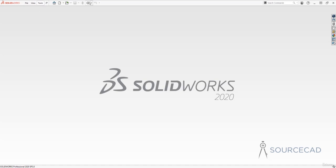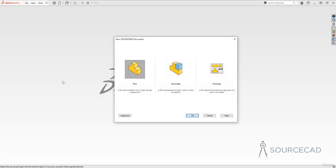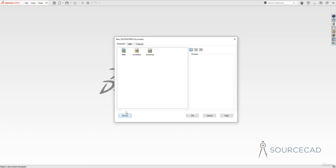Then we have the quick access toolbar, which we'll explore in a moment. So let's now start a simple blank template. I'll go to File and New. And here you can select a template like Part, Assembly or Drawing. This is the novice view. You can also switch to Advanced view to see more templates. These three are the same templates which we saw in the novice view, but we have some in the MBD tab, and you can add your own custom templates in the tutorial or anywhere you want here. So I'll switch to templates, select part, and click OK.